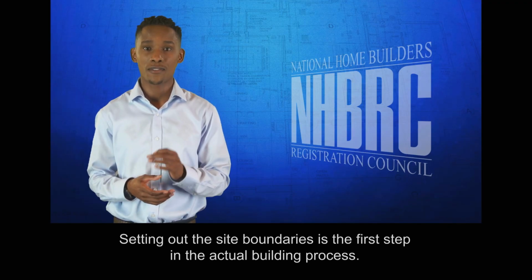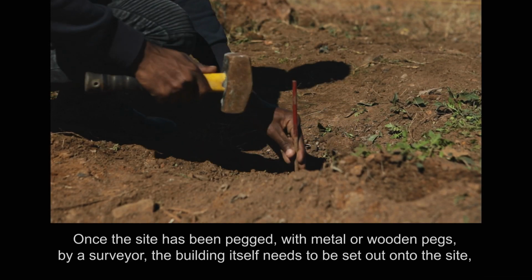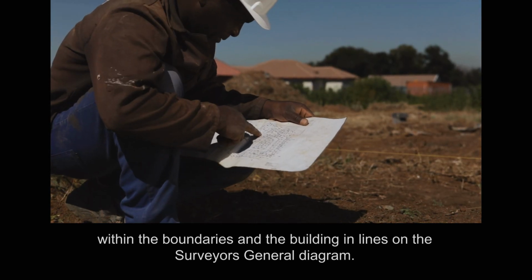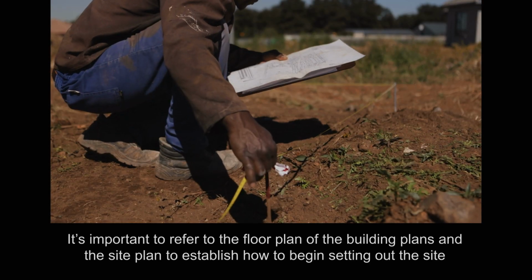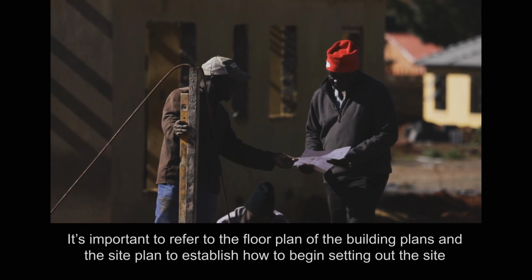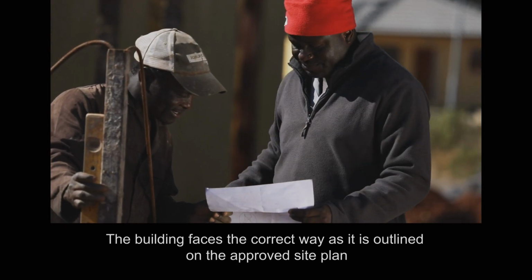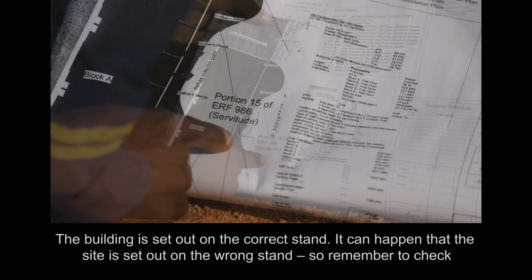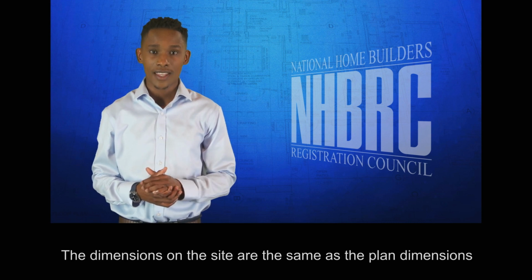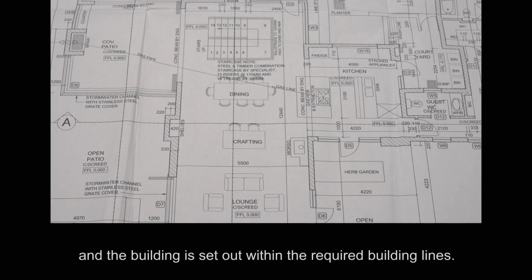Setting out the site boundaries is the first step in the actual building process. Once the site has been pegged with metal or wooden pegs by a surveyor, the building itself needs to be set out onto the site, within the boundaries and the building lines on the surveyor's general diagram. It's important to refer to the floor plan of the building plans and the site plan to establish how to begin setting out the site. You need to ensure that the building faces the correct way as it is outlined on the approved site plan. The building is set out on the correct stand. It can happen that the site is set out on the wrong stand, so remember to check. The dimensions on the site are the same as the plan dimensions, and the building is set out within the required building lines.